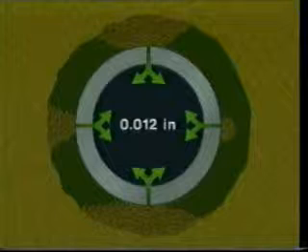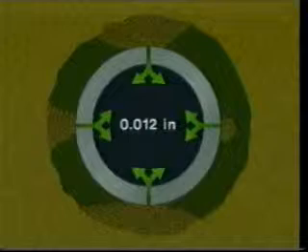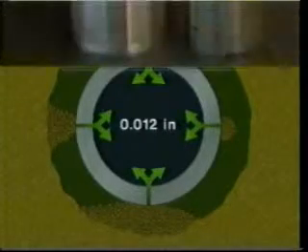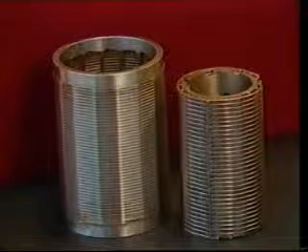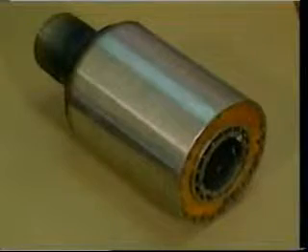In more competent formations, bridging may be inefficient because most of the sand grains pass through the slots as they separate from the formation. This results in slot enlargement caused by sand erosion. In such wells, a smaller slot may be utilized to retain the majority of the sand grains. Slot sizes smaller than 0.012 inches are often considered too small because of the difficulty in cutting slots this size. When slot sizes should be this size or smaller, wire-wrapped screens, pre-packed screens, or filter screens are recommended.